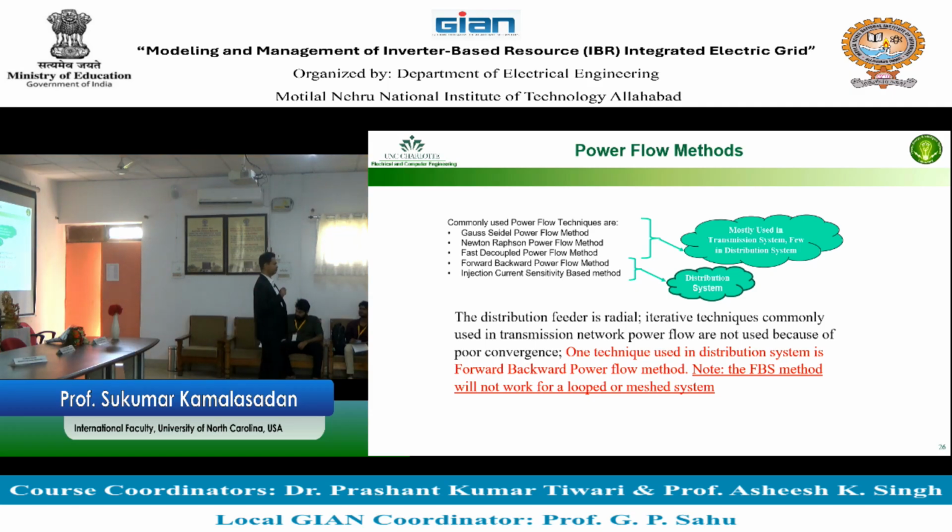Most of the time, in transmission system, this one phase power flow is done on a positive sequence representation. Okay. Why no negative sequence? Because there is no unbalance generally represented in the transmission system, and no zero sequence since no unbalance is represented in the transmission system. So the transmission system models are generally called positive sequence models. Those positive sequence models are used to run the power flow.